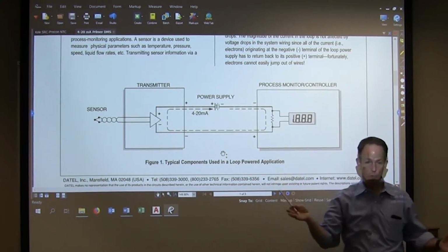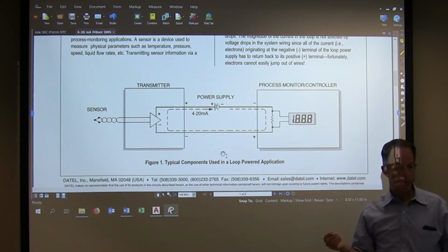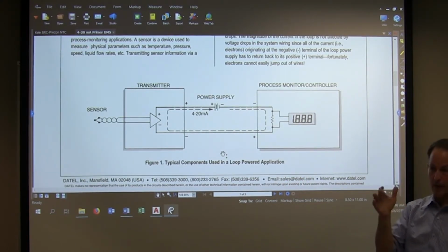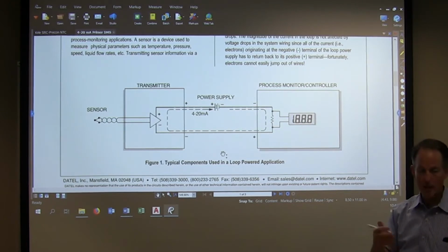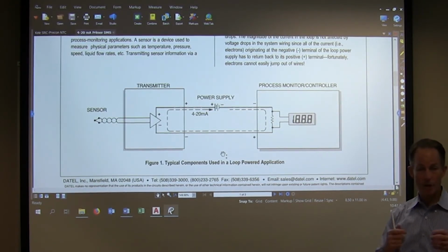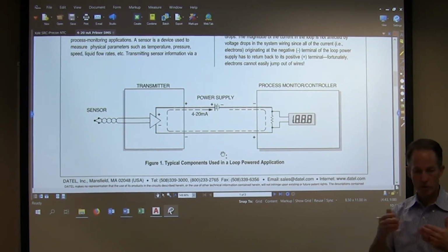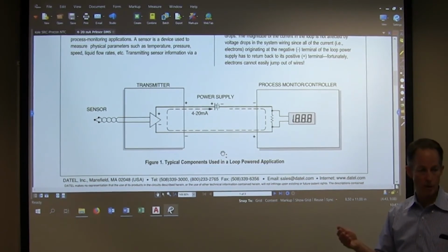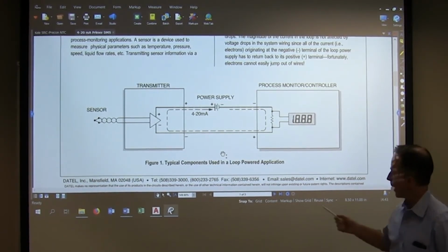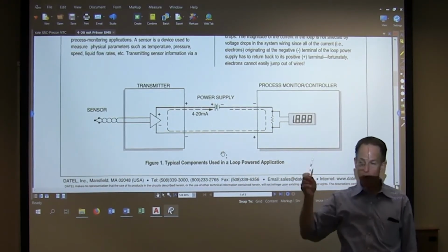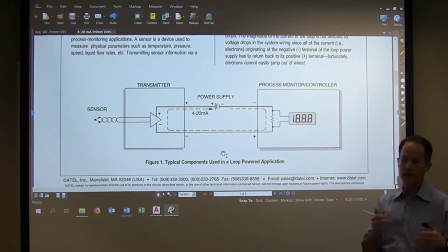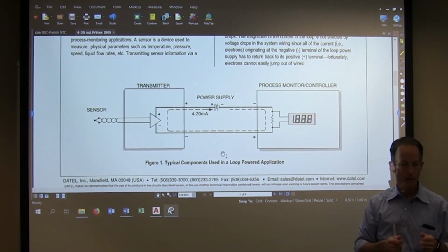Now those are numbers we use a lot, right? 0 to 10 volts is right in our area of working with stuff. It's a safe voltage, it's DC, it doesn't take a lot of componentry to build a transmitter or a power supply to generate that. And so my power supplies don't have to be huge. I've got a signal, 2 to 10 volts. I can read that really easy with a meter. That's a pretty readable value.